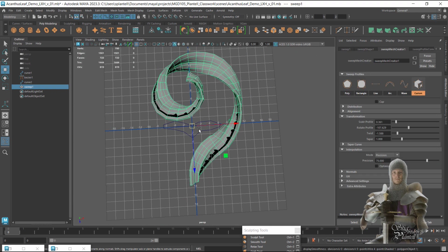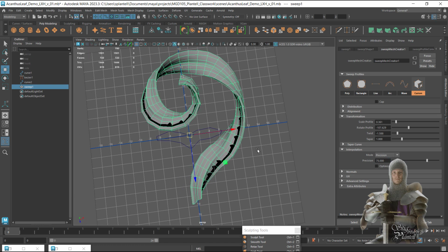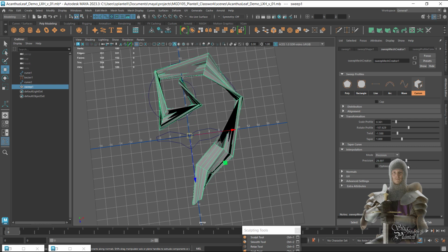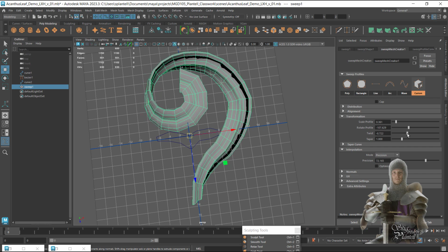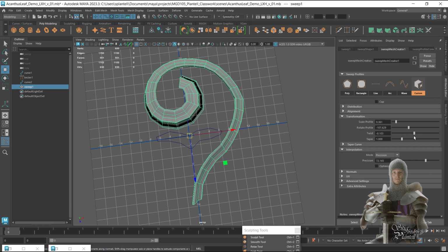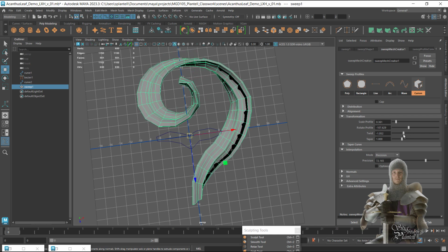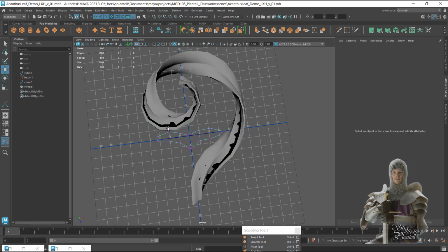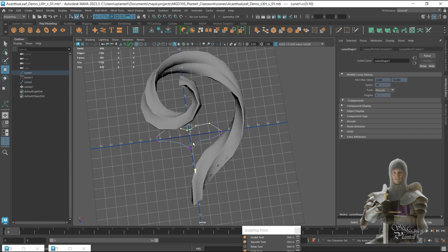That is because of the precision. If you go to the precision, by default it's 75%. If you raise that up, those things tend to go away. Maybe I'm twisting it too hard. Let's relax the twist a bit here and see if we can get back to something. You know what? I'm going to put it where I thought looked beautiful. Looks beautiful there. I'm going to adjust the profile.